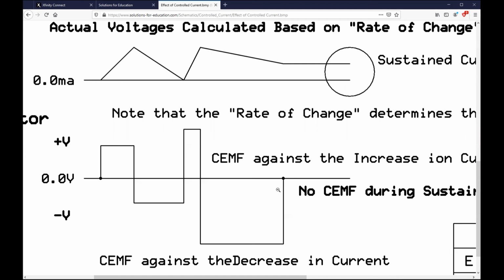In other words, when the motor is spinning, the current that's there is changing, and as it changes, it produces a counter EMF, which keeps the current, shall we say, sheltered down. And if you stall the motor, all of a sudden there is no counter EMF, and the current jumps up to about 3 to 4 or 5 times what it should be, and the windings go smoke. Is that what you're talking about?